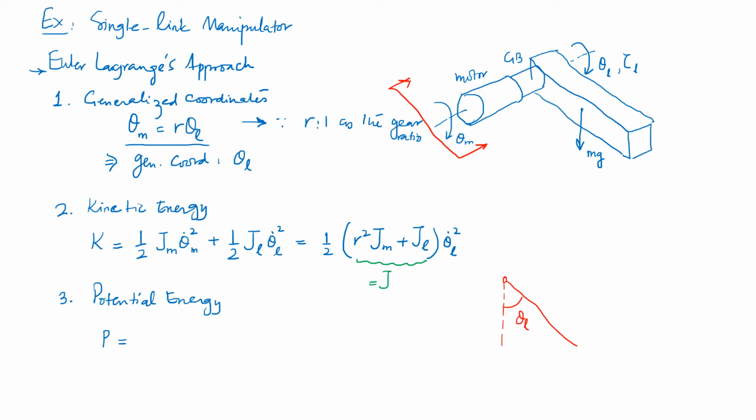And in that, if the center of mass is structured over here, which goes down like this, mg over here, I need to identify what is going to be the length from the pivot point all the way to that center of mass, and let it be L. Now, if you define that, you can say that this point where the mass is centered is going to move in this fashion, and I'm interested in finding out what is this height from this point all the way to the lowest point over here.